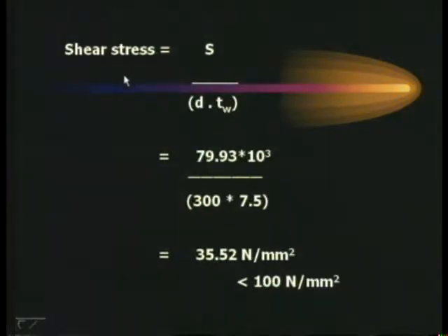And now because of the shear force, we have to estimate the shear stress that would be developed. Is it clear? We have calculated the shear force, and because of that shear force, let us estimate the shear stress which is resulting. I remember I have told you that the shear is entirely borne by the web.